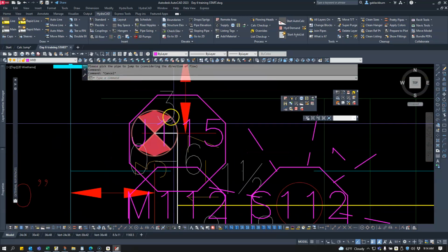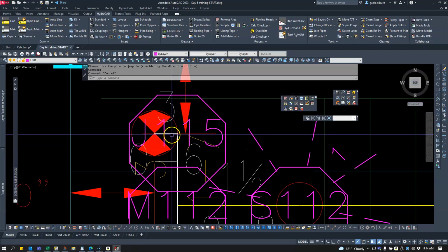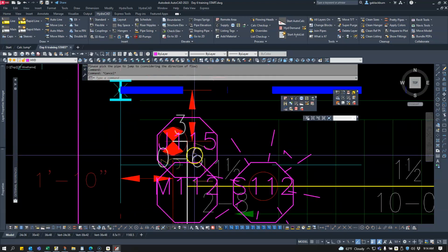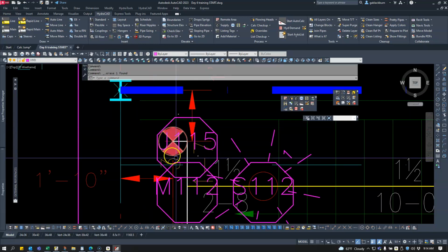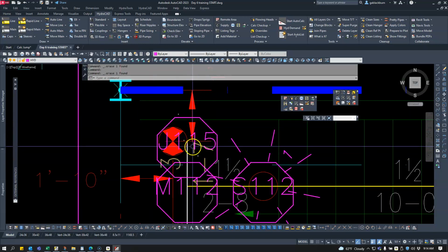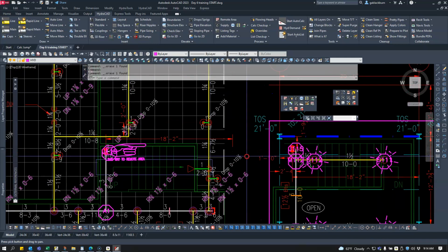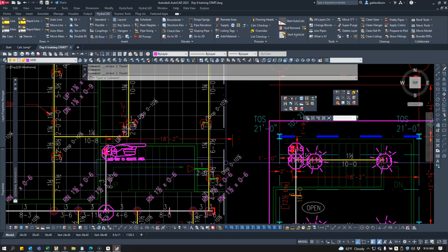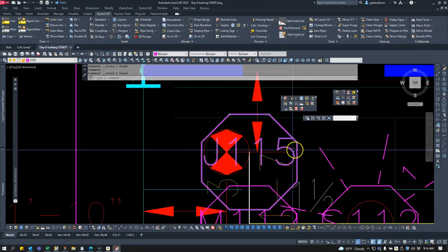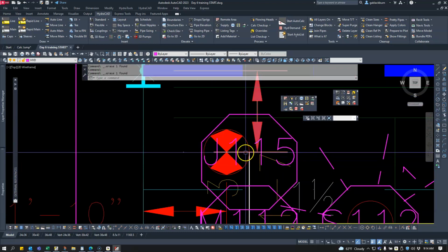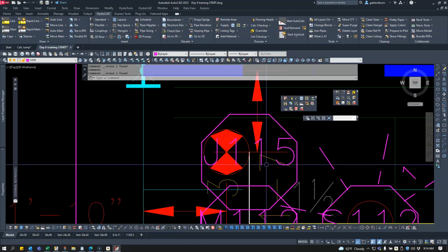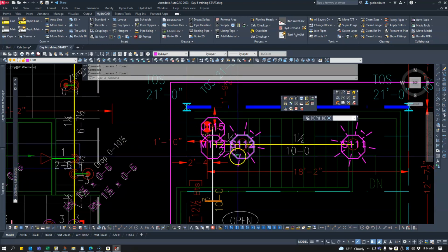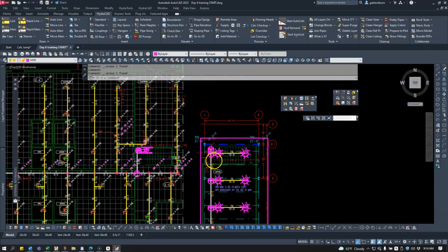Now, I also believe the program may not understand. I think the jump has to go to a dead end pipe. So we'll find out real quick. You know what? I'm going to delete this pipe, this 3x06 piece, let's get rid of that. And that way now it's jumping there. So now we're not having any pipe duplicated. So we're jumping from here, we're jumping to here, and I'm just not going to show the back-to-back elbows. When you get ready for stock listing, you might want to go back, redraw them, and then break your fittings in at that location. But for this purpose, we're not going to do that.